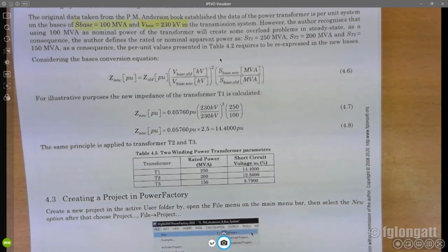If you use 100 MVA as a base, and then you say that the transformer is 100 MVA, well, we will have a problem, because if you look at the load flow data, one of those generators is sending 163 megawatts across the transformer. That means if you install a 100 MVA transformer, you will be destroying, you will be burning that transformer. Okay?